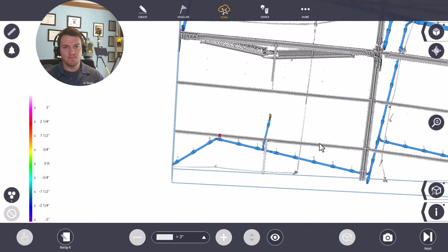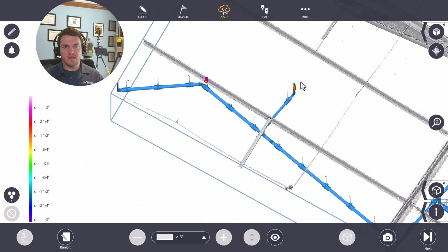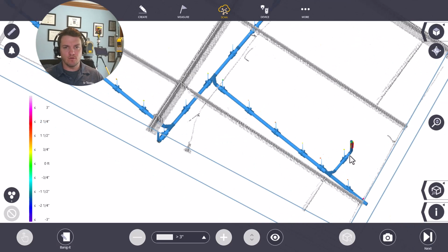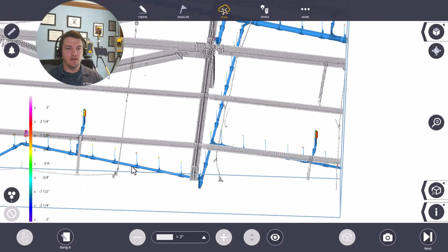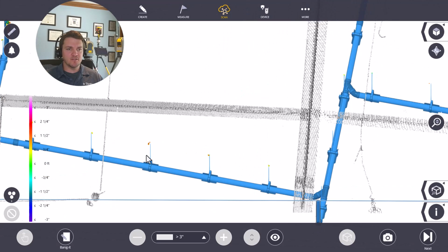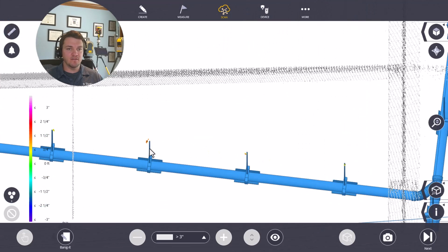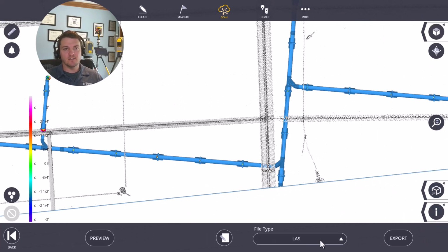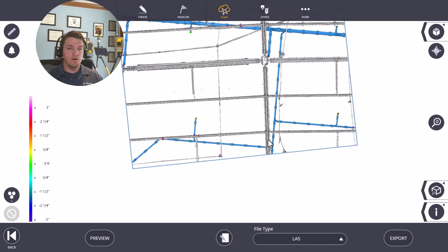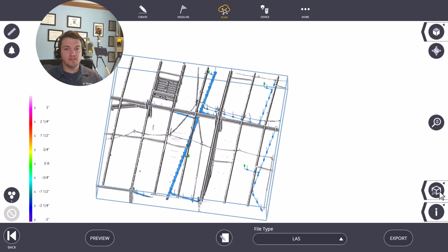comparison for that section. So this will pretty easily highlight where my sleeves are, making sure they're in the right spot. I'd make it a bigger inspection area if I wanted to do that as well. And here you can actually see even those bang-its and the all thread that's there is coming in. And I can then export that out as an LAS or E57, which can be brought into Recap and then in Navisworks, or really into any Trimble product.